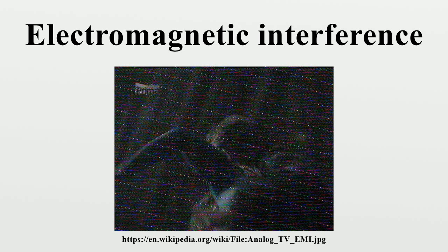Multiple CRT computer monitors or televisions sitting too close to one another can sometimes cause a shimmy effect in each other, due to the electromagnetic nature of their picture tubes, especially when one of their degaussing coils is activated. Electromagnetic interference at 2.4 GHz can be caused by 802.11b and 802.11g wireless devices, Bluetooth devices, baby monitors and cordless telephones, video senders, and microwave ovens.